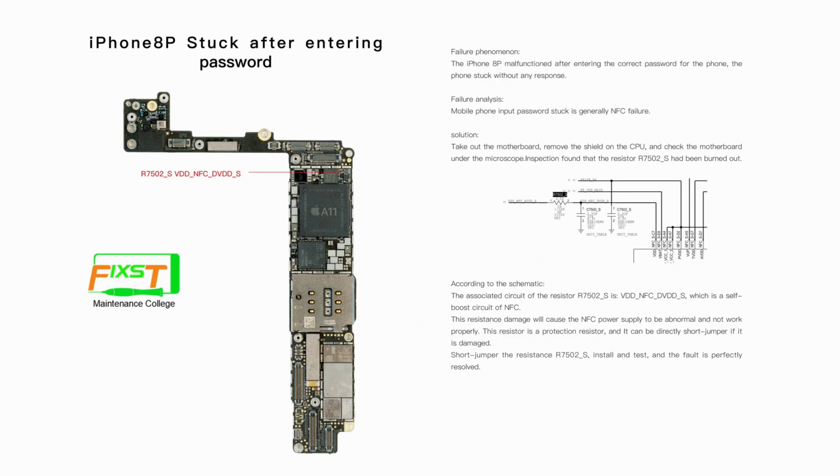This is the iPhone 8 Plus. The phone is stuck after entering the password. Maybe you guys have met this problem. When the phone is stuck after inputting the password, it is generally caused by an NFC problem. The solution is to take out the motherboard, remove the shell of the CPU, and check the motherboard under the microscope. After our testing, we found the resistor R7502. This resistor has been burned.